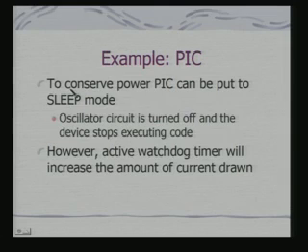So, let us take some examples of processors where these modes are available. First example is PIC. We had studied PIC. So, PIC has got, to conserve power, a sleep mode. In sleep mode, the oscillator circuit is turned off and the device actually stops executing code. You cannot really execute code on that device.